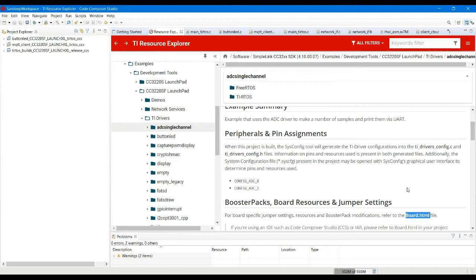Okay, now I showed you the last day that the ADC basically has 4 user channels. Actually it has 8 user channels, but 4 of them are for internal use, and the rest are for applications. So for the application part, you have channel 0, 2, 4 and 6. So what we will do, we will basically instantiate ADC 0 and ADC 1 as two ADC objects. Okay, and alternatively we will collect data from the channels.